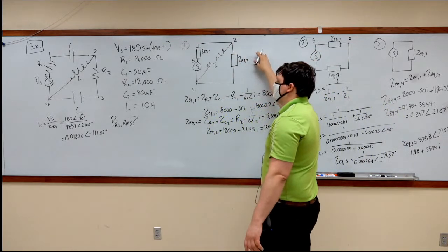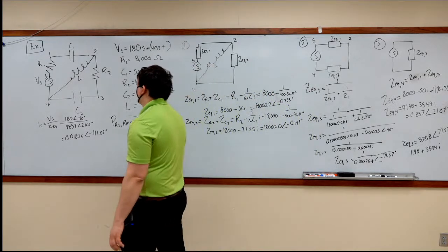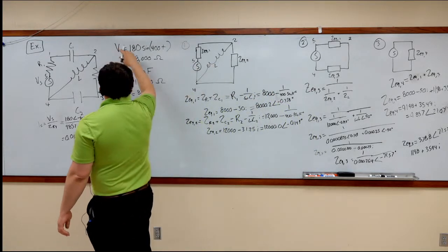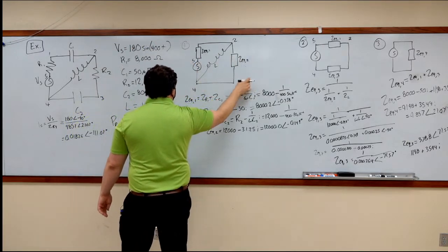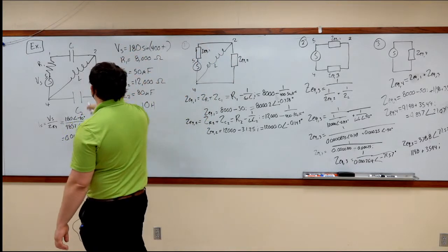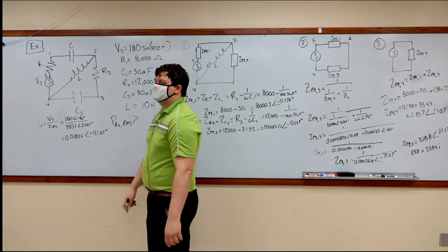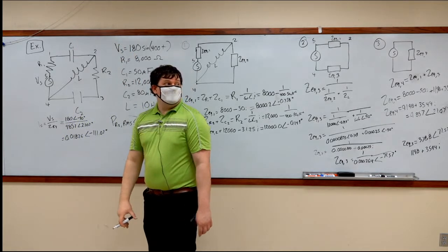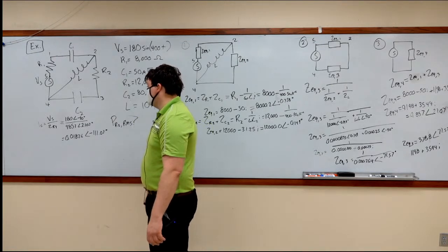That is the voltage across ZEQ2. Once we know the voltage across ZEQ2, then we can calculate what the current is through ZEQ2 using the ZEQ2 value, which will give us the current through R2. We multiply R2 by the current, and that's the answer. I don't really want to do all of that. Let's call it good because we calculated IS.